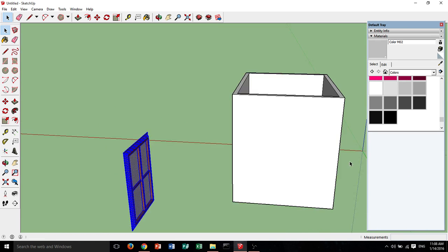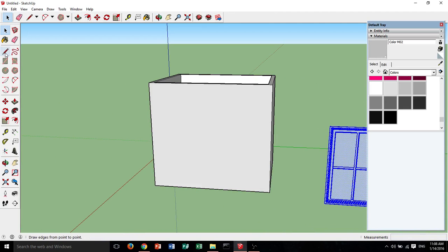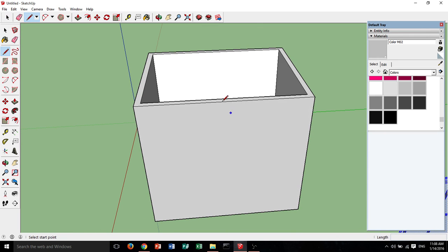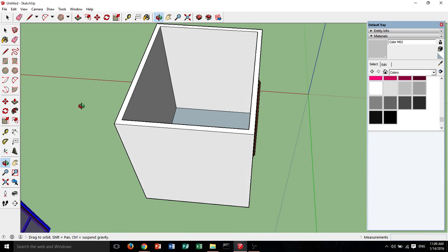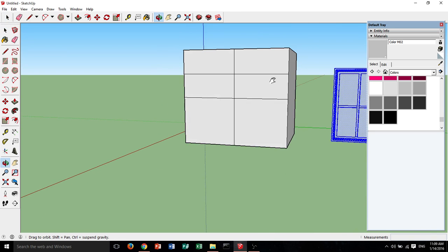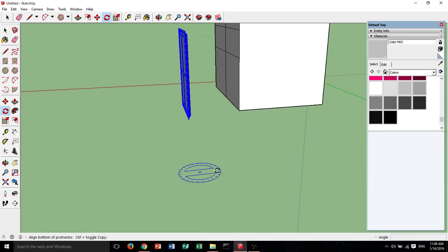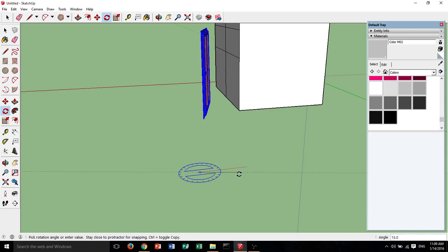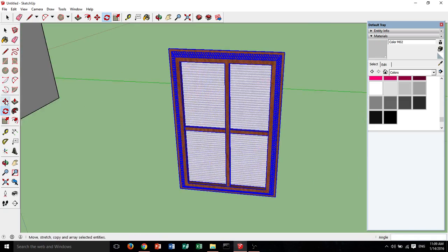Now we want this on this wall the same way as this. So let's use our line guides again that we made earlier. Go to the mid segment, drag it down to the other mid segment, go across, and do the upper across. So the top of it went right here, as it should have. Yep, it did. So now we know that we need the very top mid segment of our window frame to attach there. Let's use our rotation tool, go off the red axis, and let's rotate 180 degrees. Ta-da! 180 degrees.